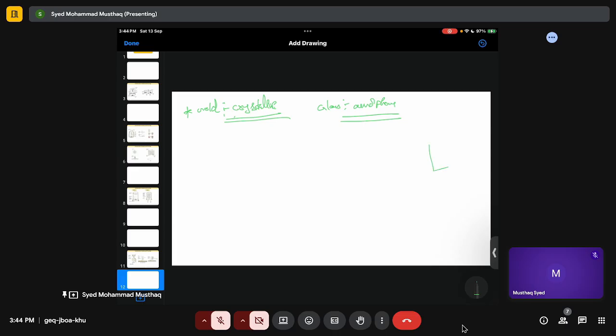How did they form it? One guy, let's say this is a stopper, and he melted gold, and then he applied a very high pressure of gas from above. It's just like taking water in your mouth and spitting it out very fast. You apply air pressure from your lungs into your mouth, such that the water comes out as a jet. Same here, he applied argon gas, which is an inert gas, from here, and when he applied very high pressure, this stopper would break. It was designed in such a way that whenever you apply high pressure, it will break. For example, he applied 50 megapascals.